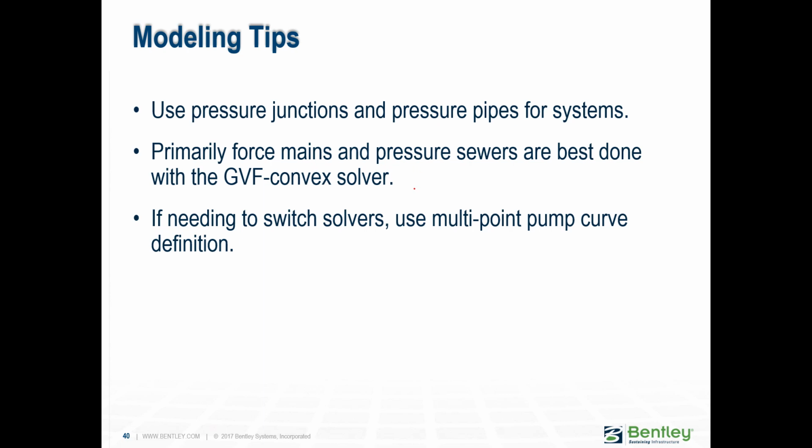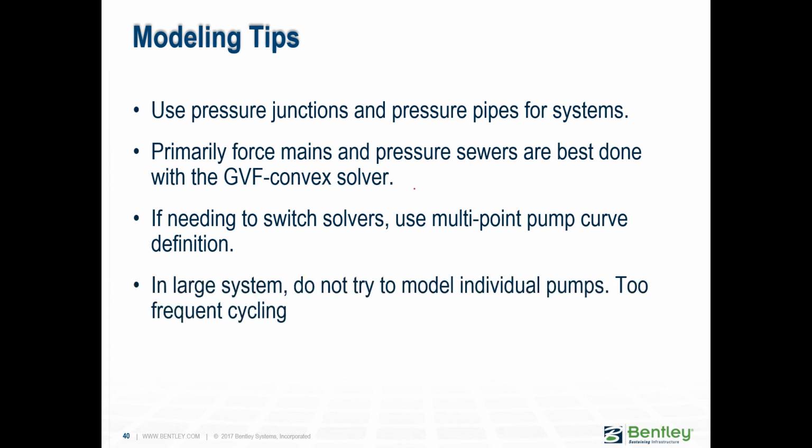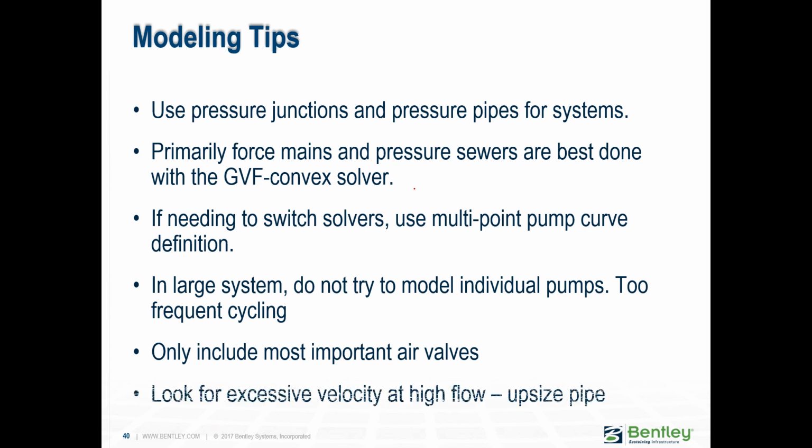If you're using SewerGEMS and you need to switch between solvers, so that you don't have to replicate work, use a multi-point pump curve definition that can be used for both solvers. If you have a very large system and you model a lot of the individual pumps, it can be cumbersome and complicated for the computational engine. So to save yourself some time, don't do the individual pumps, just do the inflow curve. And include the most important air valves that you have in the system.